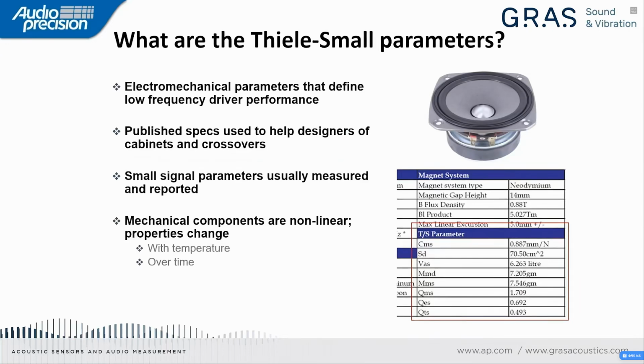Thiele-Small parameters are electromechanical parameters that define low frequency driver performance. Published specs used to help designers of cabinets and crossovers. Small signal parameters are usually measured and reported.